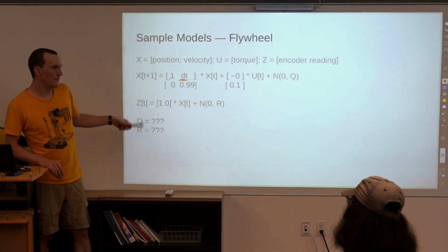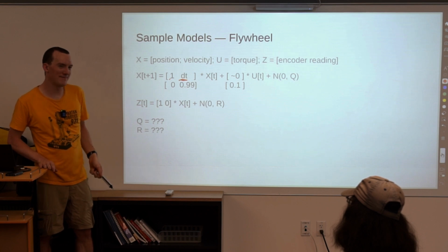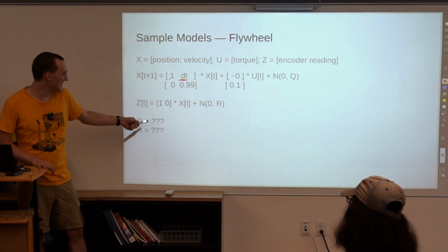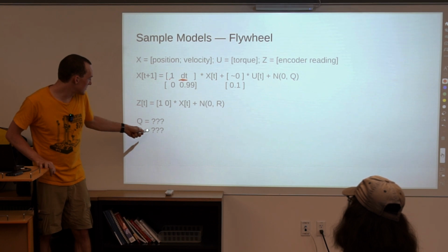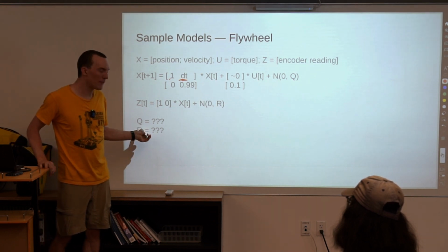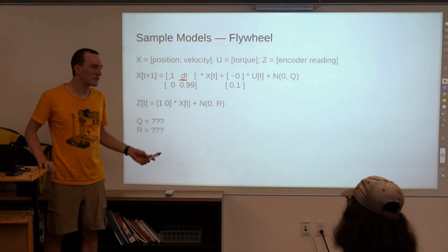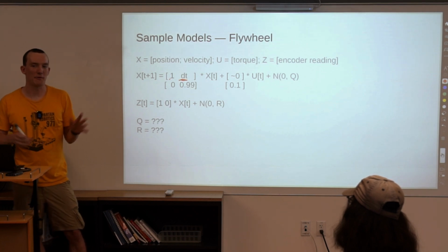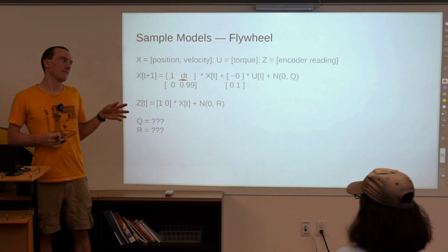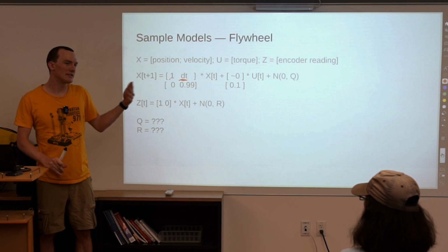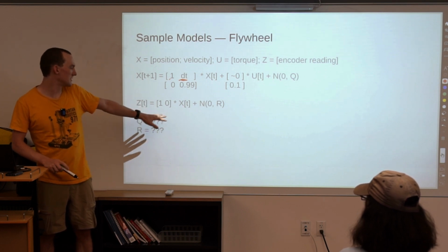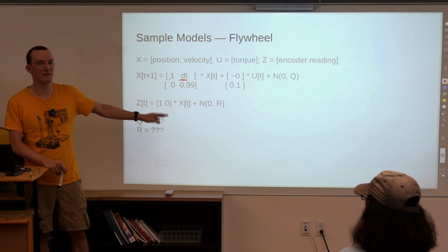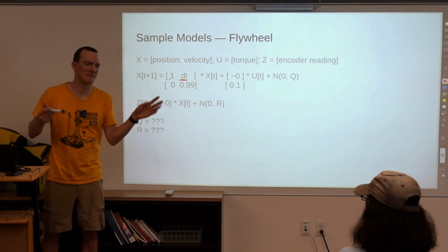Q, U, hand wave to pick. There are principled answers here. You can sometimes get a reasonable answer for what R should be. Like you might be able to just look at one of your sensors and see how noisy it looks. Honestly, where we generally start is we write out a diagonal matrix. We assume that our noises are uncorrelated between different states because, as a first approximation, most of them are.